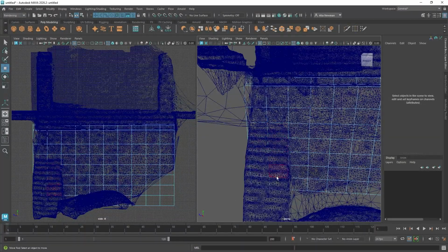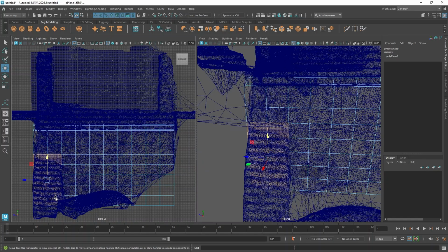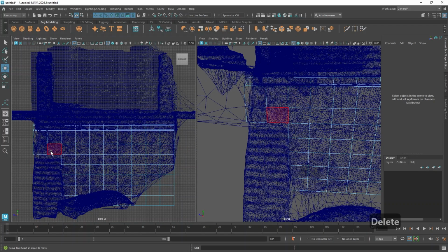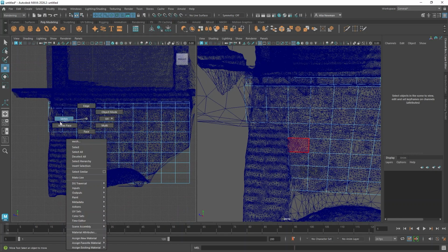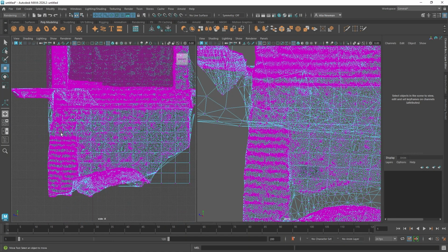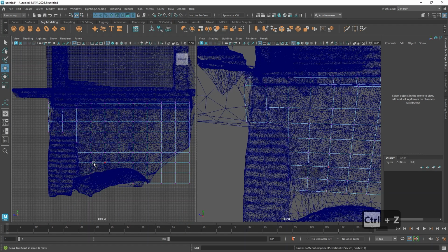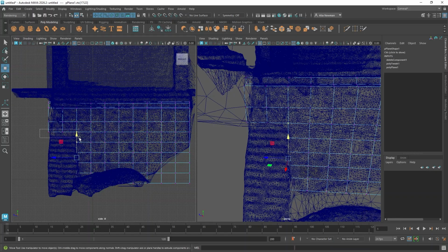But now what I can do is I can kind of change or get rid of these faces over here so that they don't get in the way of the stairs, so that I can model out the stairs myself if I need to. Ooh, let's not do that. We're in vertex mode. And I'm going to just grab these 2, 3, bring them down.